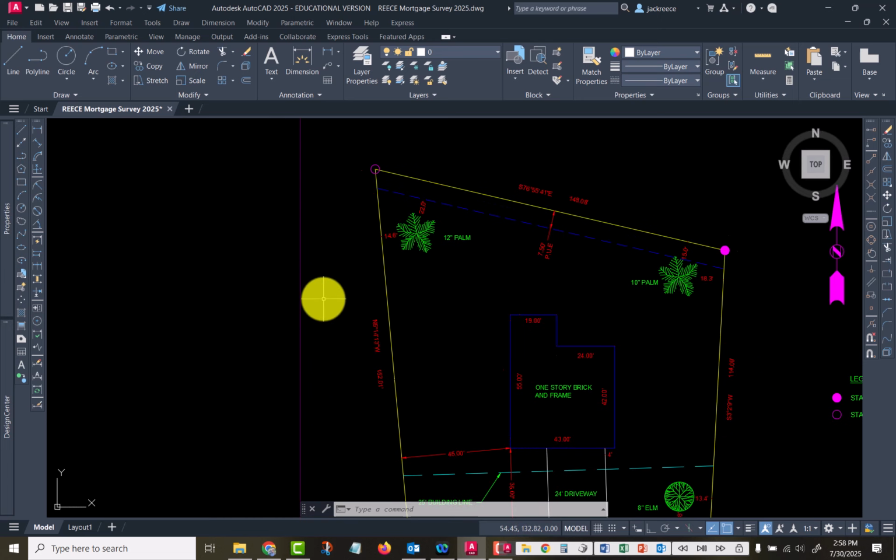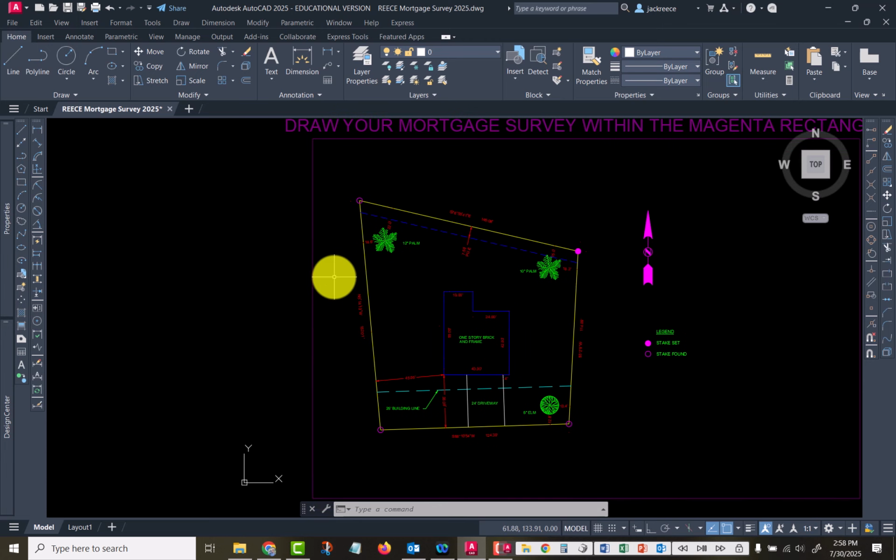Because in survey work, it may close, it may not close. When you're surveying over hundreds or thousands of feet, you may be off a few inches. However, the surveyors can calculate that, and they can put in their degree of error, and they mark that on the drawing, so it's not that big of a deal.